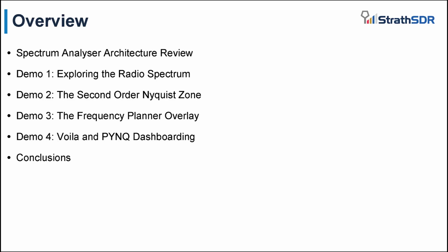The Frequency Planner has been integrated with the Spectrum Analyzer tool to aid user understanding of signal acquisition using the RFADC. Later, we will explore dashboards using the Voila Python library. Voila is an excellent tool that allows users to convert their Jupyter notebooks to lightweight browser applications. Voila is suitable for on-chip application deployment.